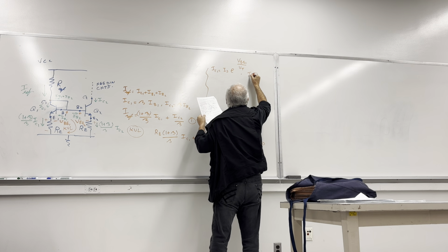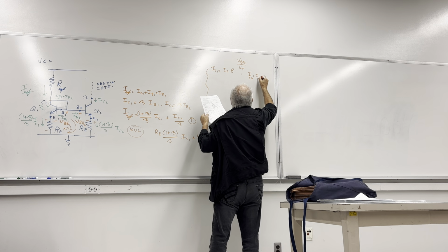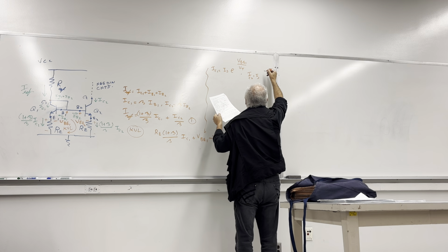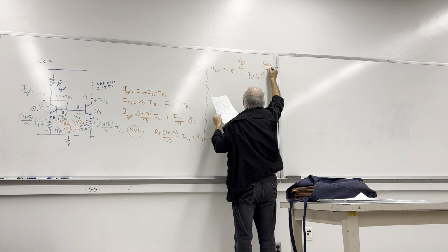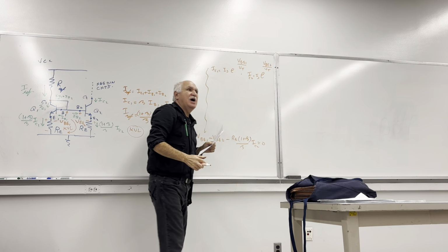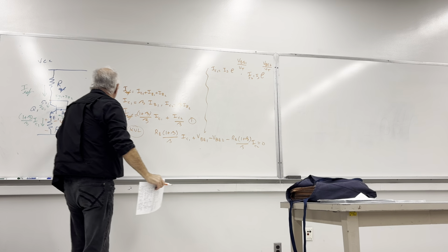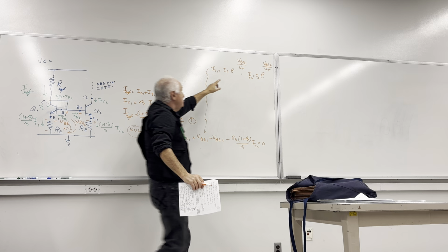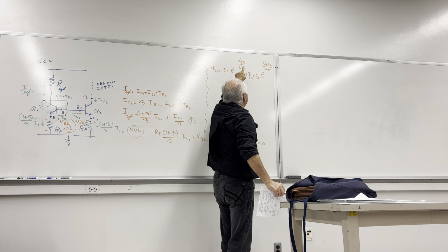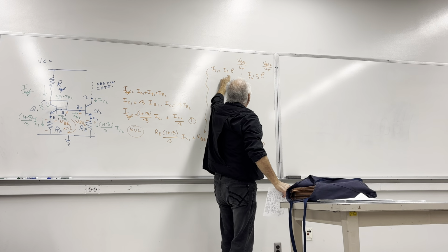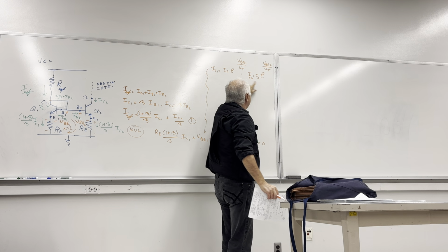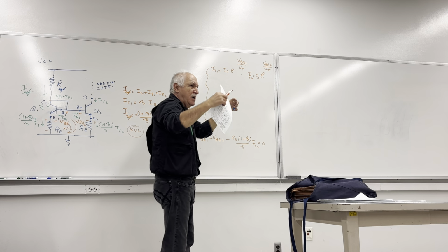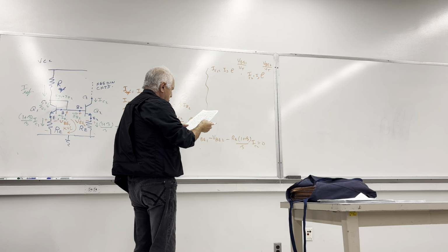And IC2 is IS, the same saturation current because they're identical, e to the power VBE2 over VT. Two identical transistors at the same temperature because they are fabricated on the same chip. Their VTs are the same, their VBEs can be different. ISs are the same. IS, the saturation current, dimension comes from the masking process.